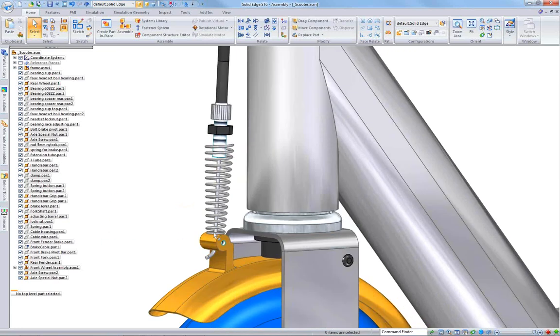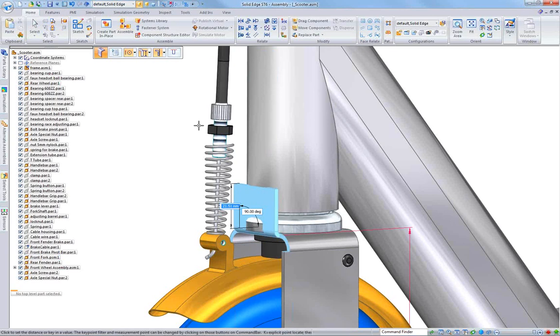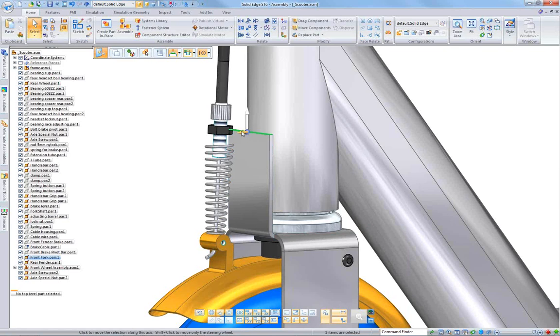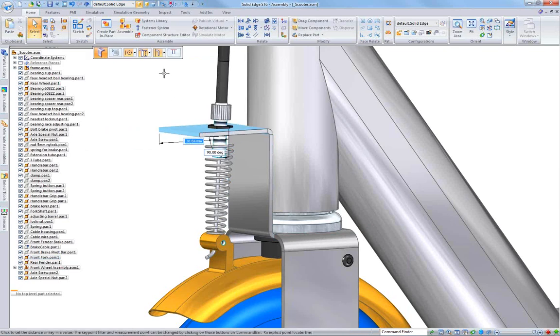So notice I'm in the assembly. I'm just picking up the edge of our sheet metal part. And if I pick this small arrow and start dragging, I can actually start dragging a flange. Now right now it's interfering because I actually want that flange to have the bend to the outside of where I selected. I want it to come right up to the bottom of that nut, and then I'm going to drag another flange in this direction. And this time I want the bend to the inside because I told it where that nut was.